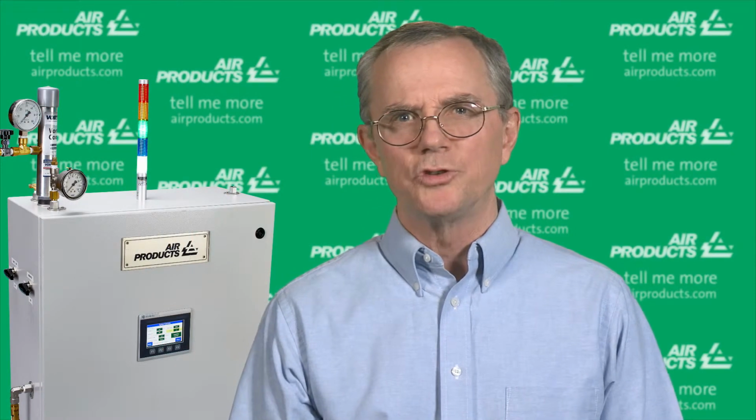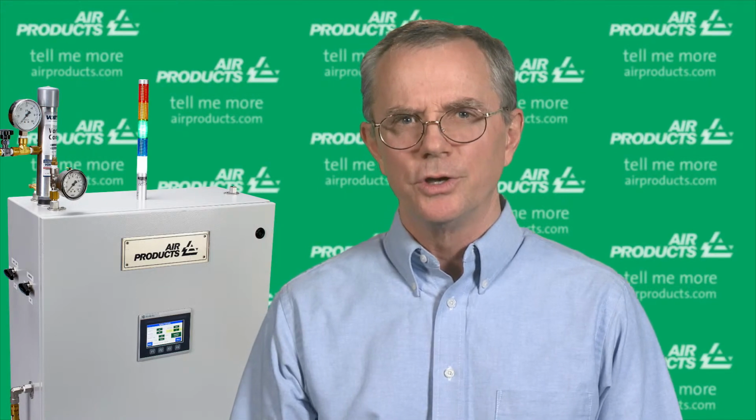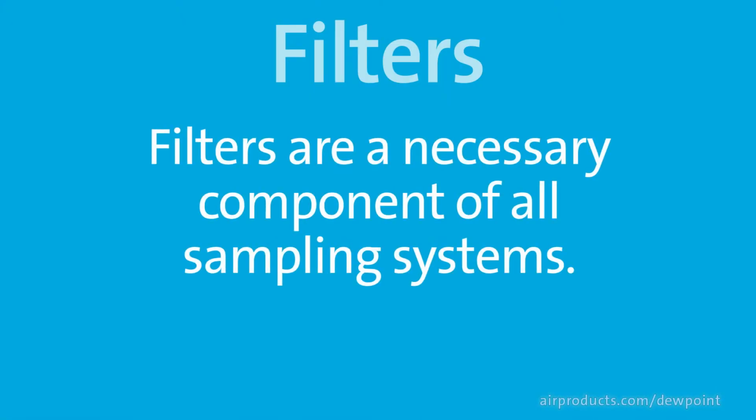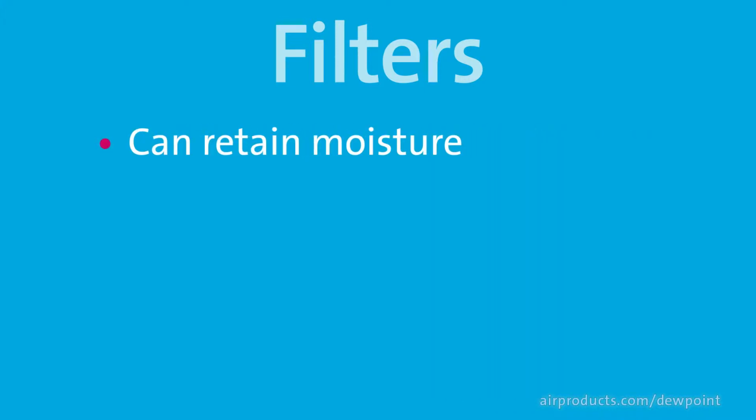Dew point probes generally have a fast response to a real increase in the process dew point. The probe response to a lower, drier dew point is not as fast. If you have a filter, that could also be the issue. Although filters are a necessary component of all sampling systems, they can be problematic because they can act as a sponge and retain moisture, especially if a furnace is burned out or idled while the sample system is kept operating.